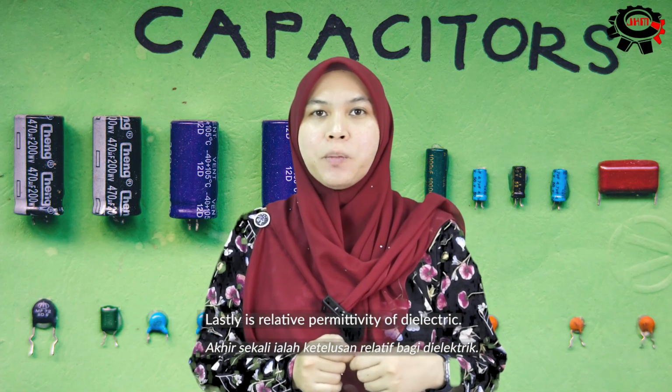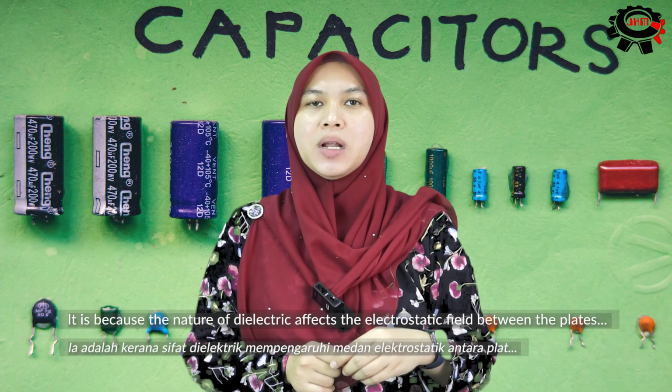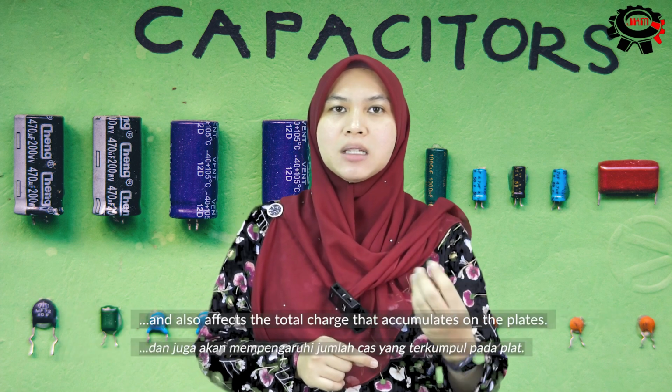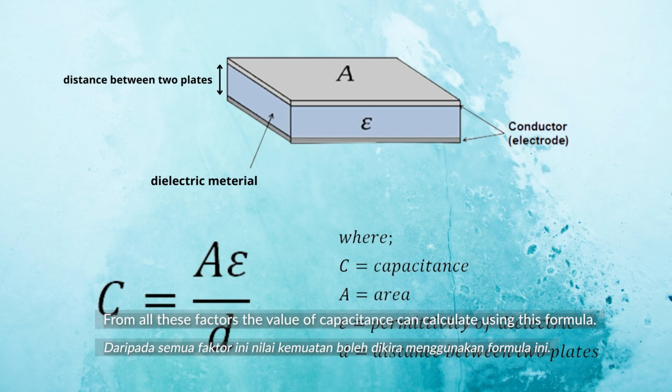Lastly is relative permittivity of dielectric. The greater the relative permittivity of the insulating material, the greater will be the capacitance of the capacitor. It is because the nature of dielectric affects the electrostatic field between the plates and also affects the total charge that accumulates on the plates. From all these factors, the value of capacitance can be calculated using this formula.